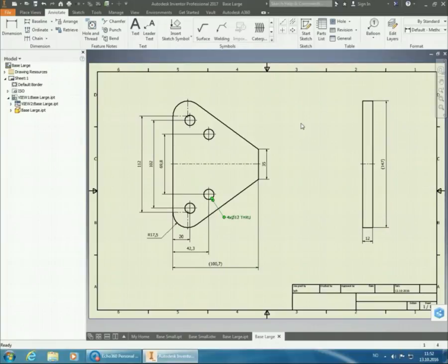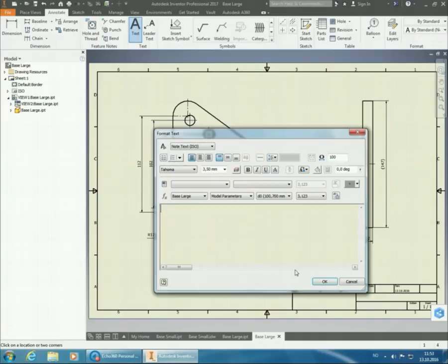So then we're over to setting our tolerance notes. General tolerances and surface finish. ISO 2768-1. We had medium and K on the previous one, so we'll use that on this one also. So medium.